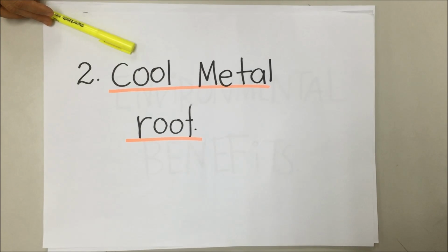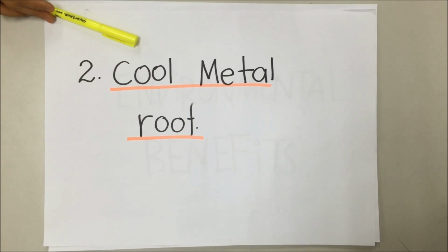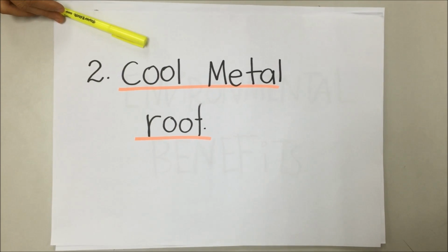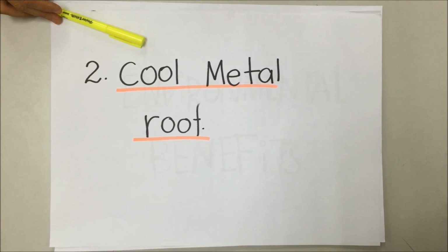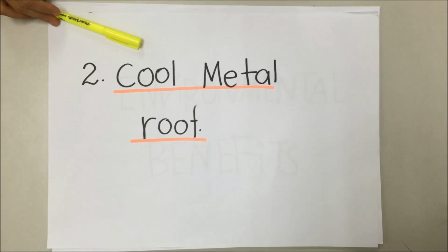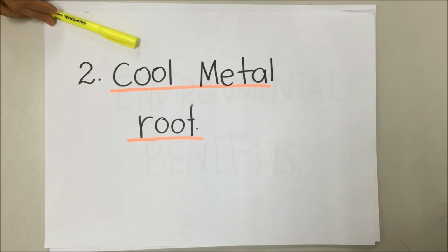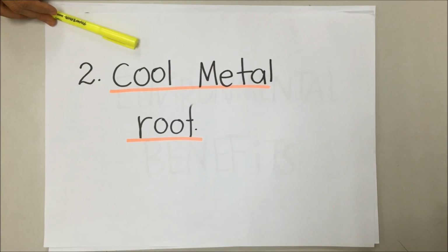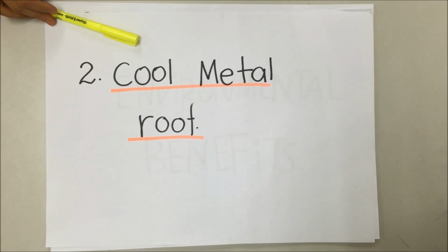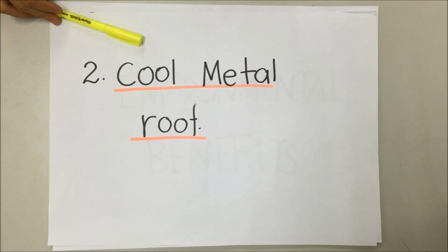The term solar reflectance is a measure of the amount of solar energy that is immediately reflected from the surface. The heat can be removed by convection as air flows over the surface or by conduction through the roof material into the shuttering below.